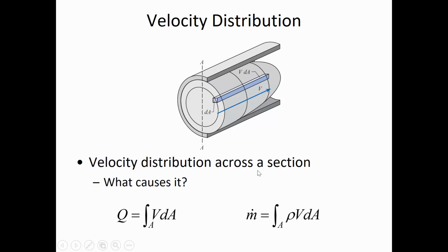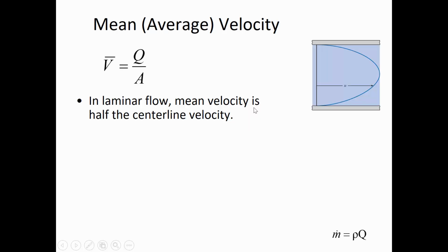It's not usually how we do it, though. We usually end up with just measuring the average velocity rather than integrating the actual velocity, and that's partly because conditions are so rarely laminar. So the mean velocity is what you've been calculating in the lab, when you use the stopwatch and see how much water accumulates in the wet well of the hydraulic bench. With the stopwatch and a certain volume, you've been quantifying the Q.